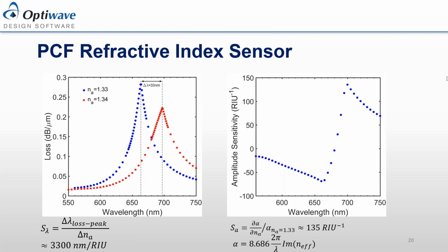If what you're asking is, can a mode solver be used in a finite difference scheme, we do have a finite difference mode solver that works perfectly well, but for these particular applications, because of the strength of the triangulation inherent to this particular FEM method, I would suggest using FEM for any kind of photonic crystal fiber analysis.